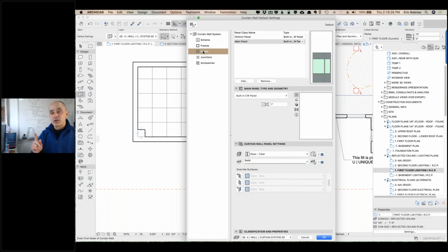And so you can select them individually and swap them out. So it can work well. When you define the curtain wall, you're going to define it in a horizontal orientation in that case. I'm not going to go into demonstrating that whole process, but you can do it. And the outline of the curtain wall can be any arbitrary polygon, so it can easily fit into the ceiling of any space. The one drawback I've heard, and I don't know if it's still an issue, is that it